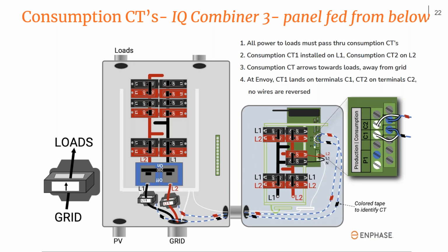Right, especially when we hit summer months and they say, my bill went up, and well, you could show them, your power consumption tripled. So this is your way of giving people information about their energy consumption. And consumption CTs are required with energy storage systems. I think they're very nice to have with your standard PV systems as well.